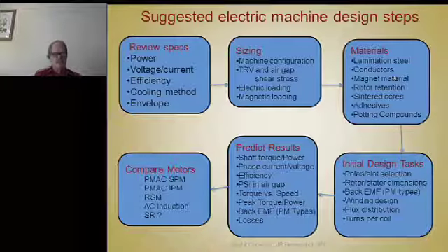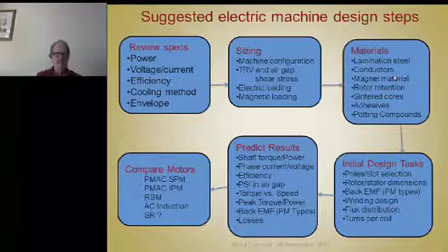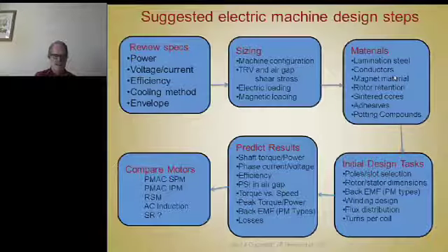Got to know what the voltage is, because current costs a lot more than voltage, whether it's in the motor or the inverter. And what efficiency goals are required, and what cooling methods are required, and what the envelope and the environment look like, and the mounting. Are there any heat sources?